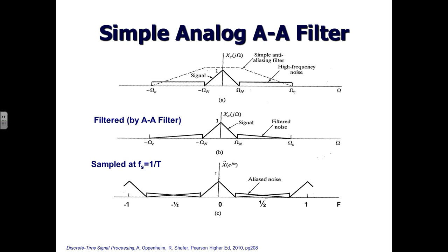So if I choose the particular one shown, we see that aliasing would in fact happen in the noise part of the spectrum. But if I choose my sampling rate wisely, then only the part of the signal that's above the bandwidth that I want to keep in my signal, the triangular part, is aliasing. So I go ahead and let the noise part alias, but make sure that my good signal doesn't alias.